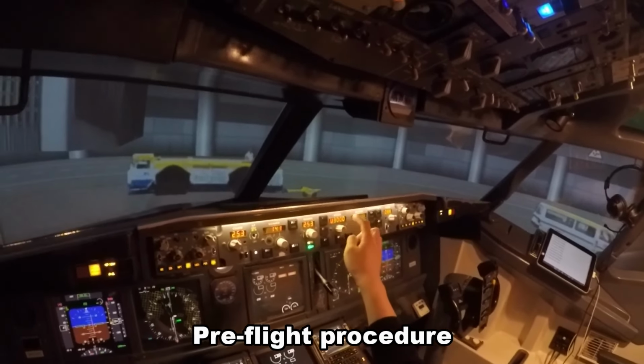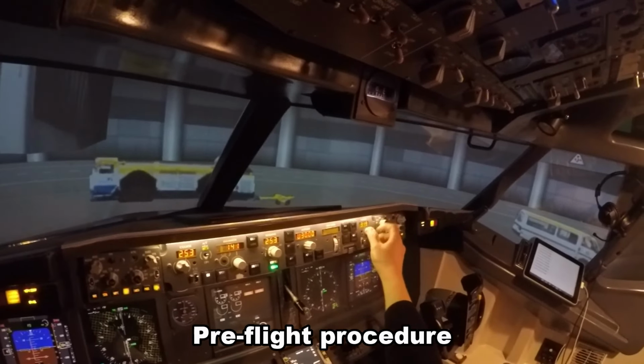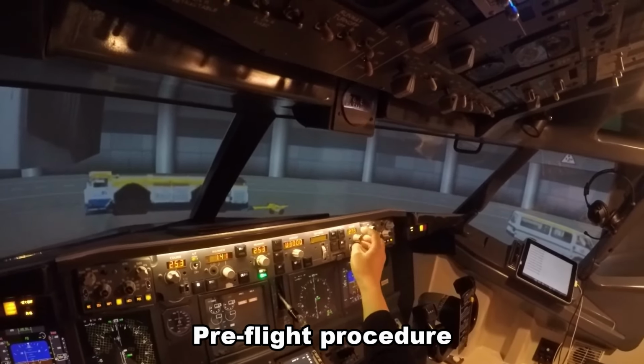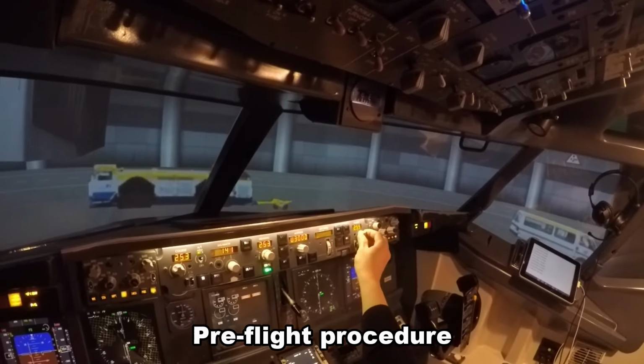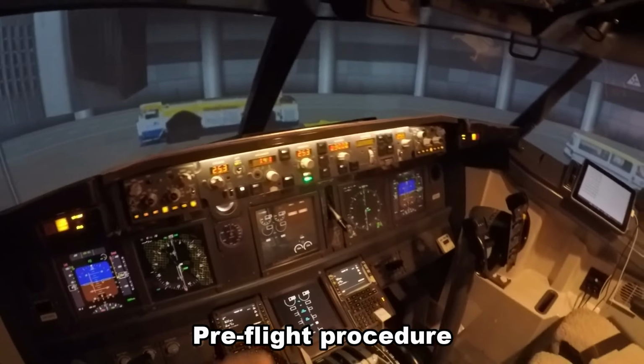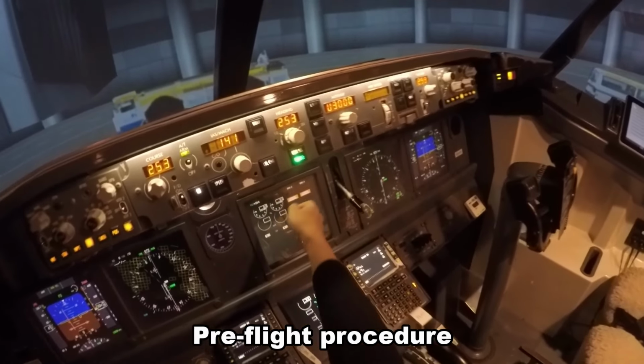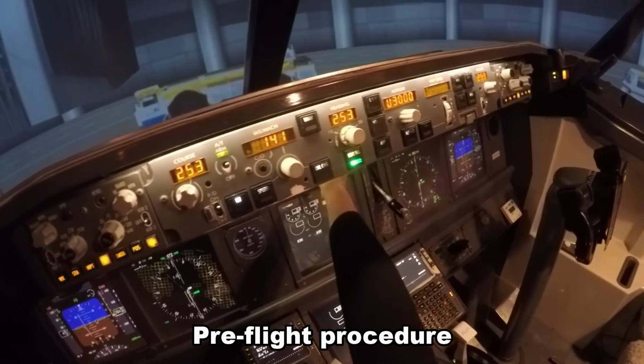Heading selected, altitude of 3,000 feet, and course heading for the co-pilot side at 253. Our flight directors are armed, which is good. Next we'll go to the main instrument panel, so landing gear is down, flaps are up.